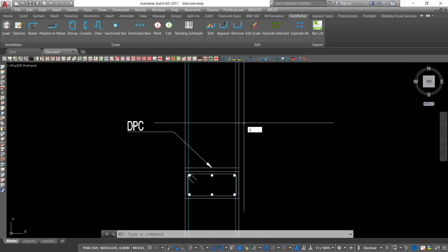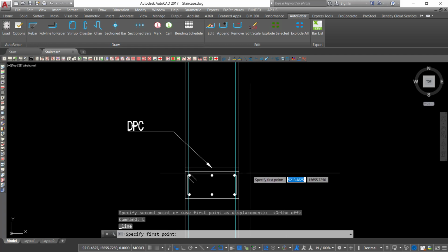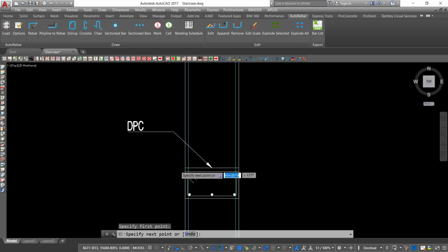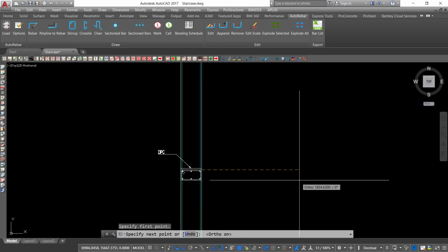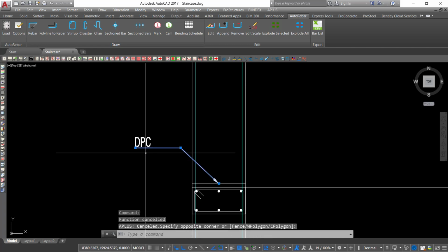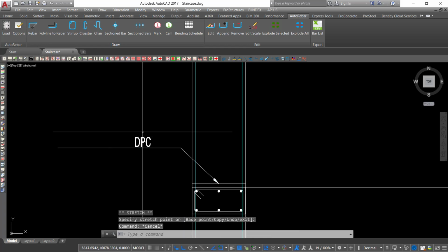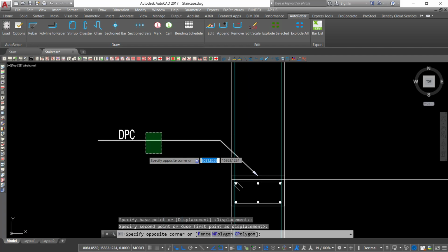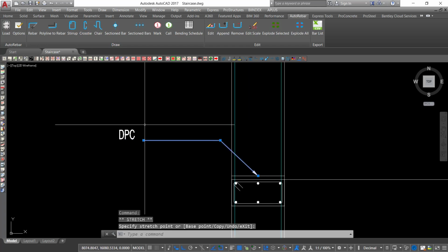Now just type line and enter on that, and we want to highlight the structural floor level. So we will come to this section here and just place our line on that spot and drag it. Make sure your ortho mode is working, and drag it somewhere there and place it right there. So from here, let's drag this slightly away to make this look more professional, and place it right there. Though it's so big, bring it somewhere there,